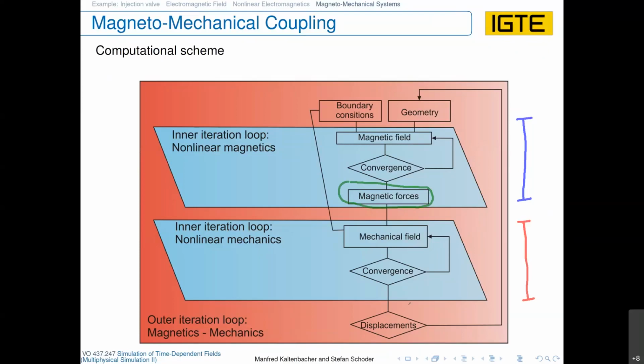And then we clearly have to check. This could also be a nonlinear computation, because you take material as well as large deformations into account within your computation of the mechanical field. And that means we then have, after this is converged, a new mechanical displacement in all our finite element nodes within the solid elastic bodies, and we check there how much the mechanical displacement has changed. If it is too much concerning our criteria, we have to go back.